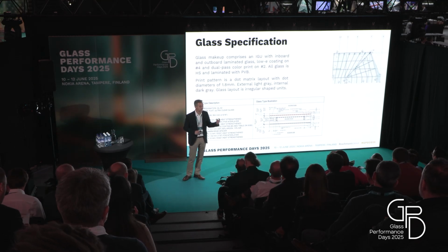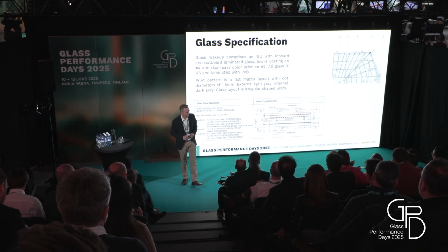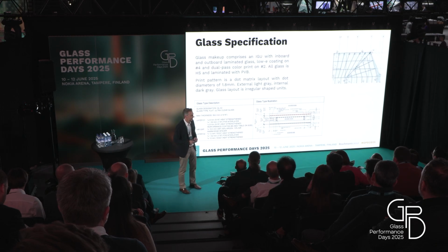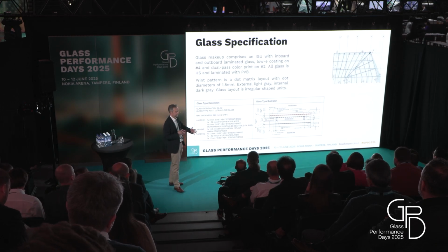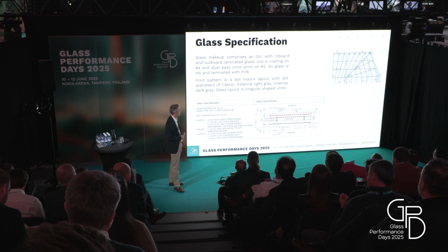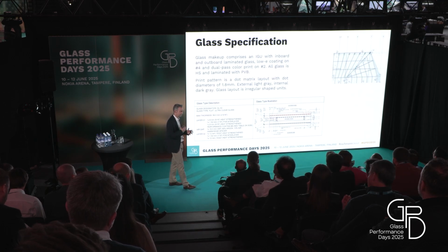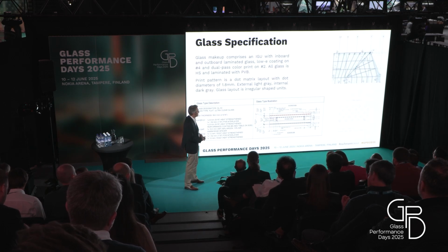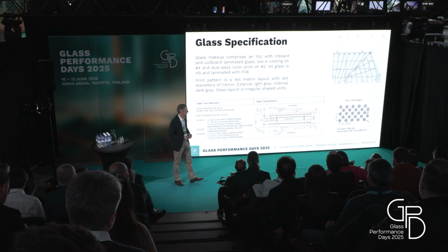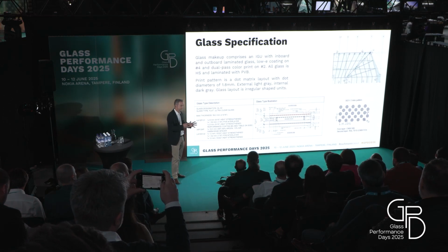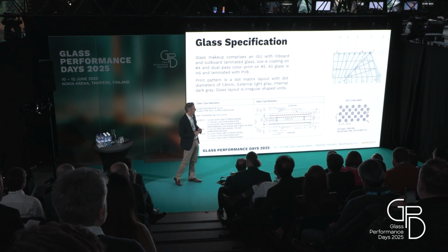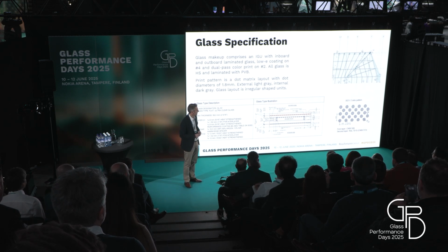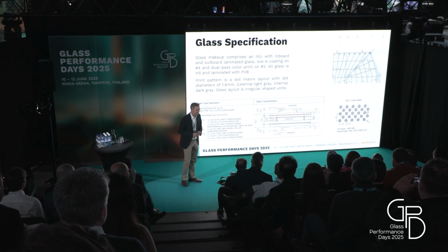We have a thicker glass at the inboard light, 2 times 12 millimeter, due to the fact that we have large spans and different kinds of geometries of panels, which all come together and may create a problem. When we take a look at the dot pattern, we have a minimal dot diameter of 1.8 millimeter, 1/16 of an inch, so small, at a center-to-center distance of 4 millimeter.